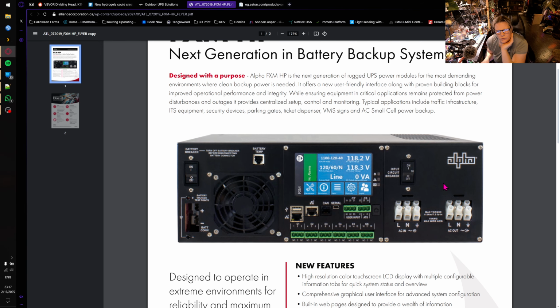So you want to use the appropriate UPS, and you want to make sure that not only are you receiving power from said UPS, but you have comms interfacing, and you have definitely configured the server to recognize the UPS and poll it. And the reason, again, why you do that is that the server will shut down gracefully once you've nearly depleted your standby power supply, okay? That will save you data loss. It'll save you database corruption. It'll save you equipment damage and all that wonderful stuff. So you just try to practice that, okay?